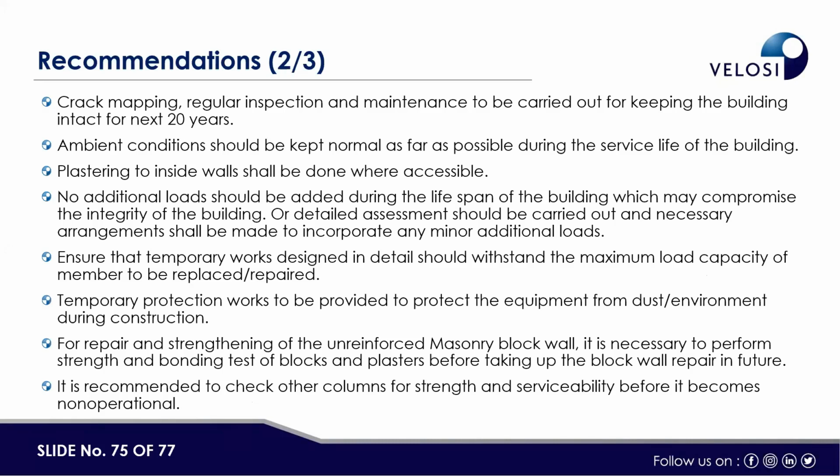So this plastering was not there, so the recommendation was given to do the plastering. Then temporary protection: if temporary works are done on the structure, then it has to be analyzed before carrying out such works. Then if any construction is to be done which produces excessive dust or similar, then proper protection of the critical members or equipment should be